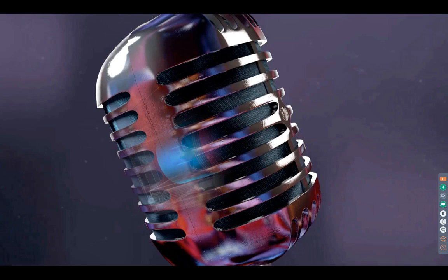may be under the grill or hidden behind a screen or something. But to make a directional mic, you need to allow sound to strike the back of the diaphragm, and the Unidyne element was the first to do that. So.